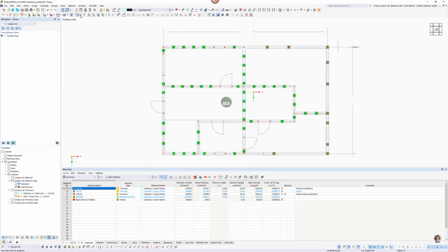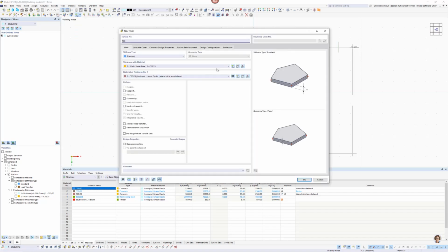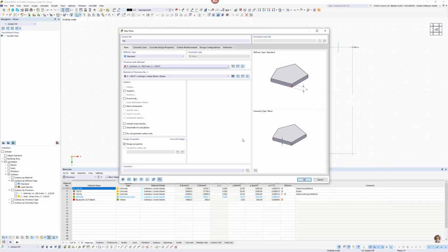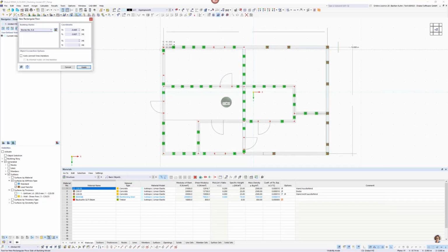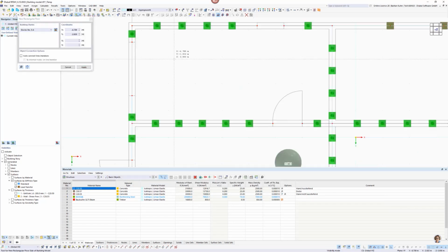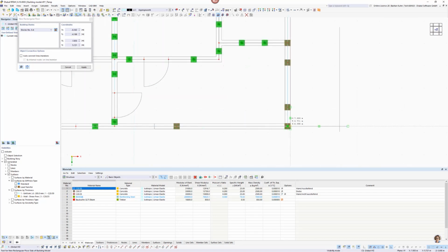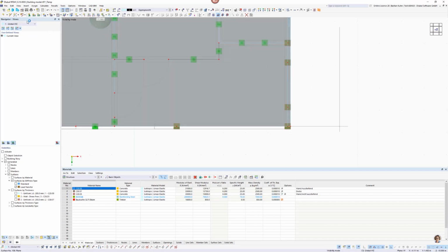And the last part is the modeling of the floor. Well, we choose it rectangular to keep it simplified and define a new thickness, uniform, floor with a dimension of optimistically 250 millimeter thickness, and go from the left top corner to the right bottom. Oh, that's not good.